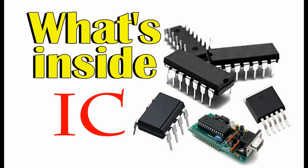Hardware accelerators. DSPs often include hardware accelerators such as multiply accumulate (MAC) units, designed to perform common DSP operations efficiently. High clock speeds. DSPs typically operate at high clock speeds, enabling them to process signals in real time. Specialized instruction set. DSPs come with specialized instruction sets tailored for signal processing tasks, which can significantly enhance processing speed. Efficient memory access. DSPs are designed to efficiently access memory, with features like circular buffering to process continuous data streams.